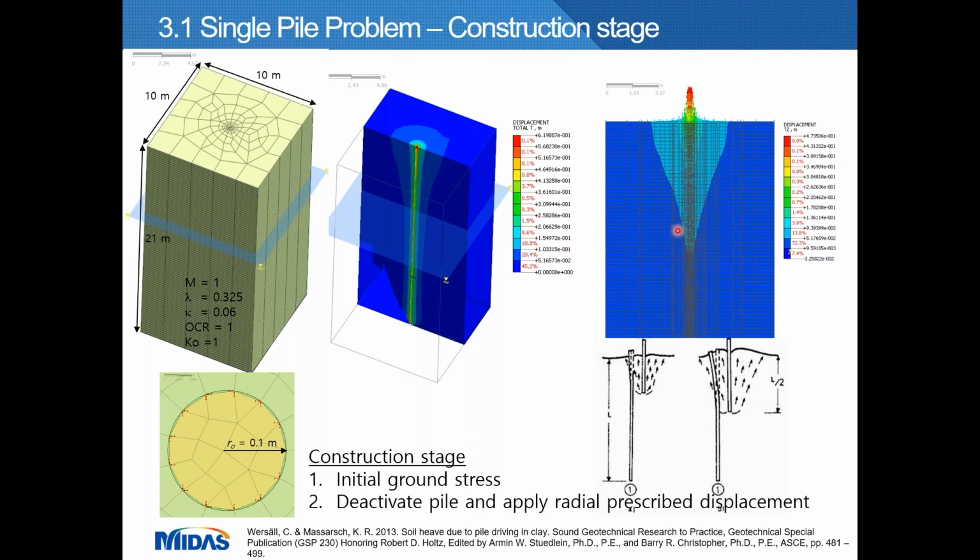And if you plot the vertical displacement of the model, you can see that the soil is actually heaved around the pile in a manner similar to that reported by Massarsch. This model is very useful when you want to model the heave of the soil due to installation of another pile in soft clay.